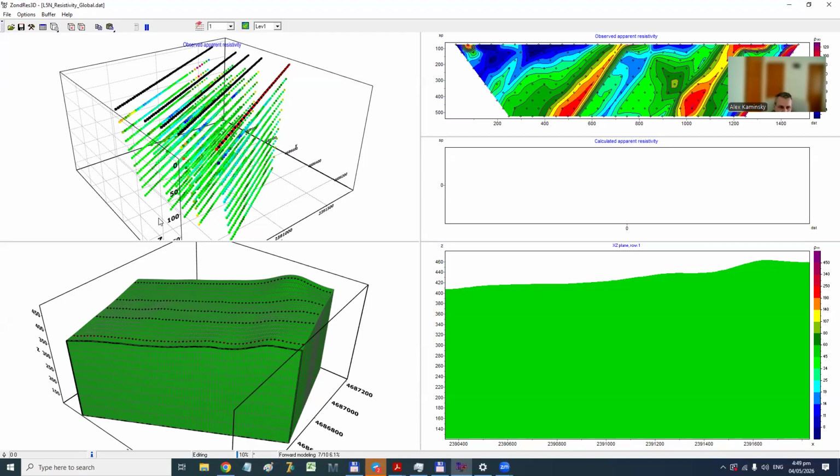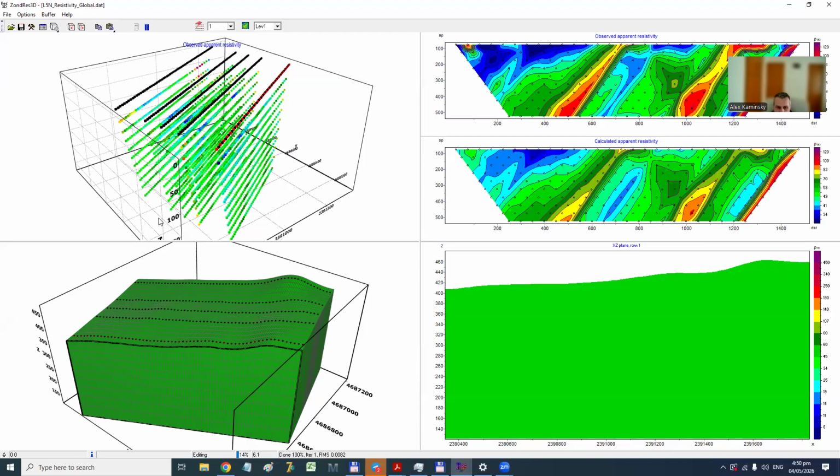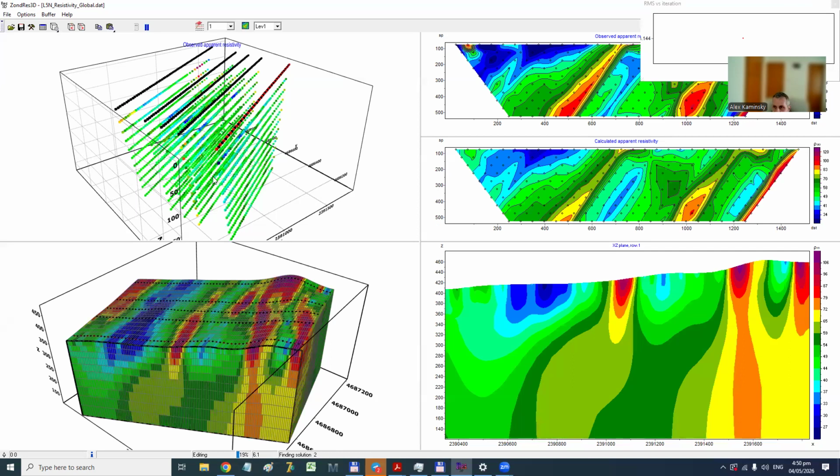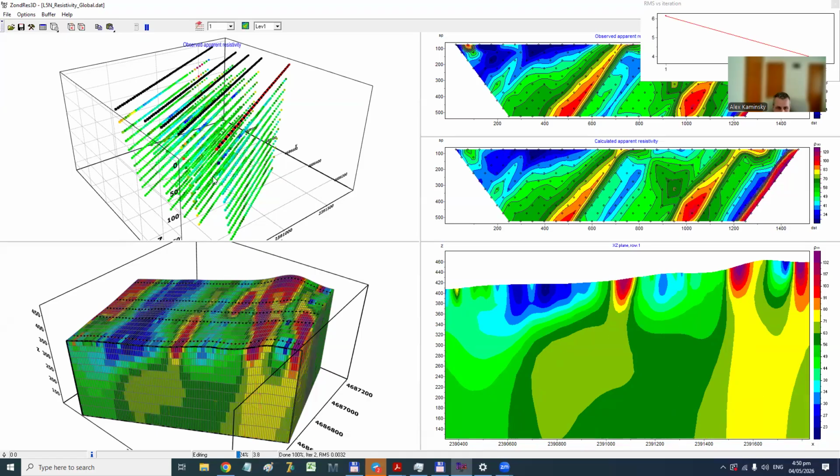But if you have very few lines for a very big model, so for example a very sparse system, an iterative solver can be better for this case, and it does not use so much memory. Plus, you don't need to do some massive calculation on every iteration.